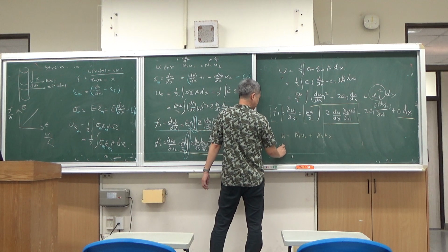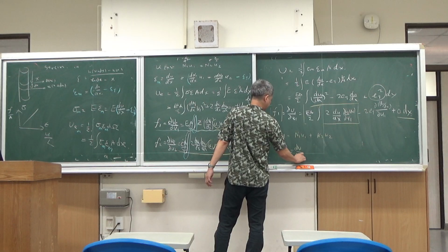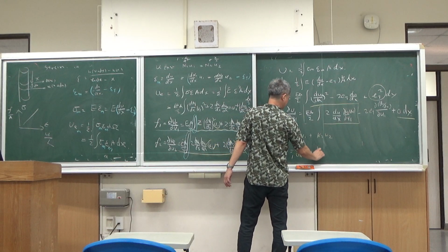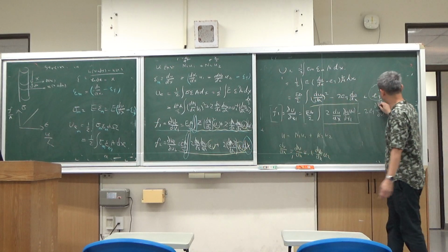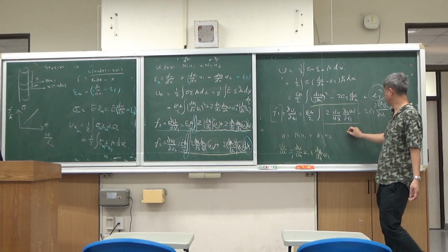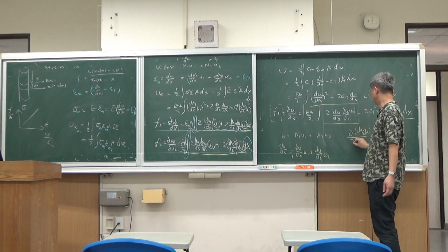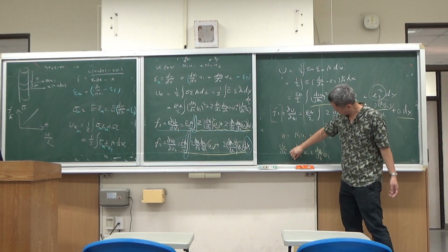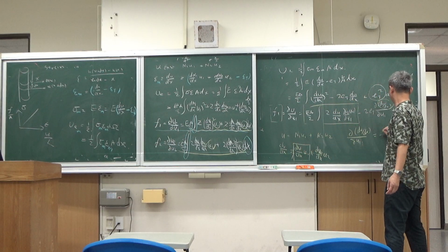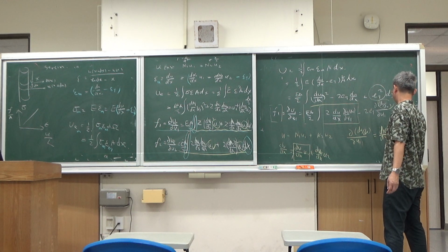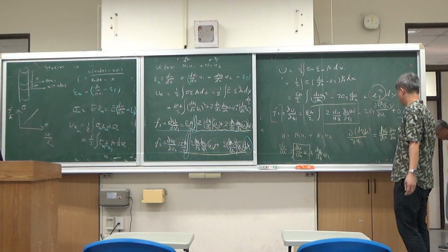If you write the expression du dx, it is dN1 dx U1 plus dN2 dx U2. If you now do the partial differentiation with respect to U1, you are only leaving out this term, dN1 dx times del U1, and the other term is 0.